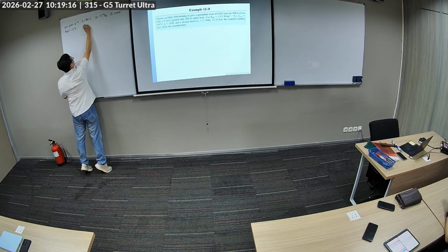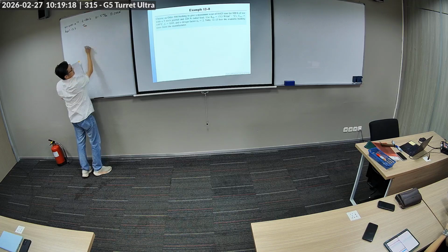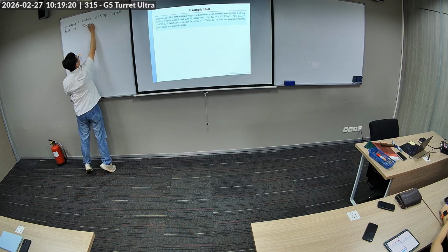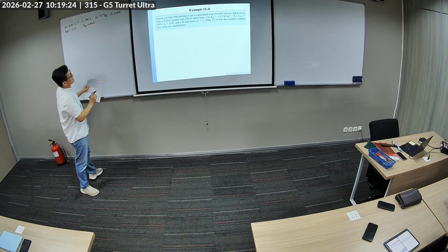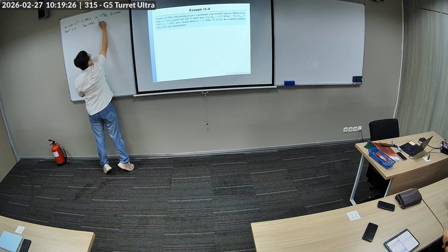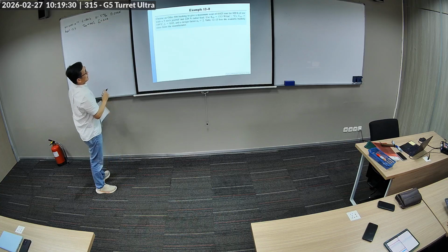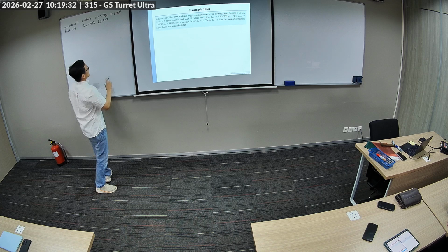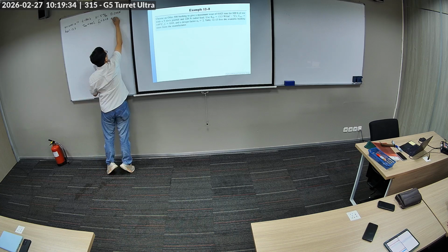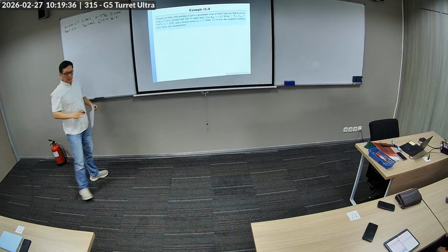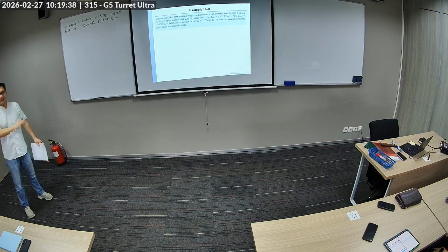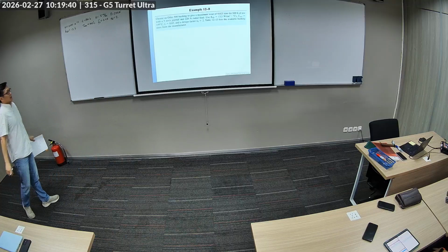Okay, Tmax. That's the allowed temperature up to 149 degrees Celsius, pretty hot. Static friction, 0.03. Design factor, again, think of it like application factor, safety margin, they're all the same.